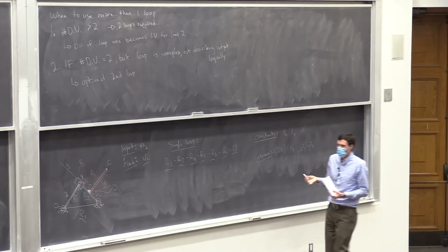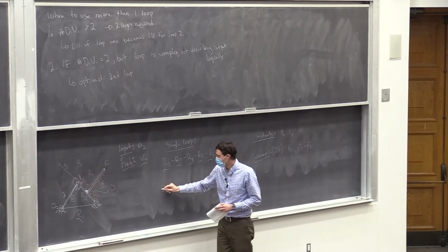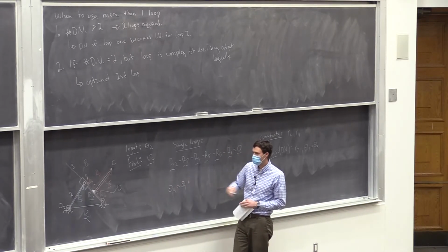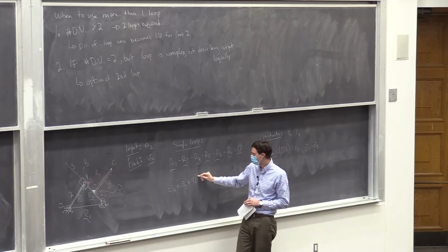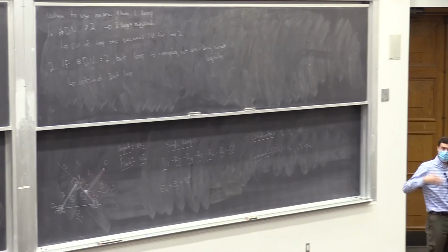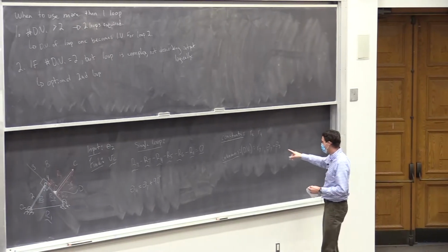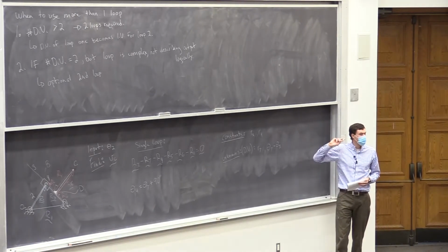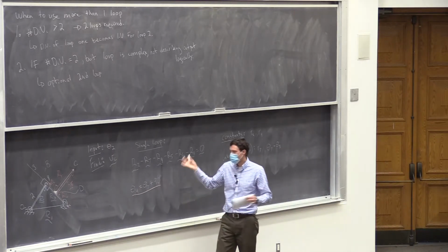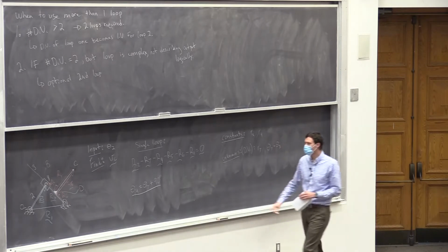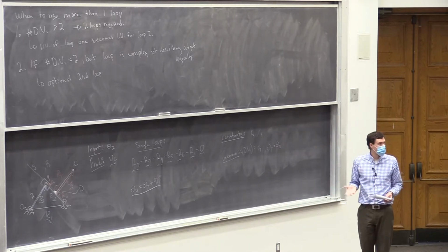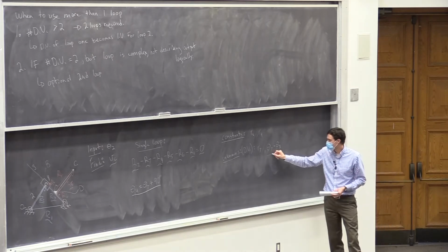So that's like a relationship that we know. Theta 4 equals theta 7 plus 90 degrees. So that's like an additional relationship that we know. So it's up to you to decide if you want to call that an unknown, you can. And you're going to need more loops to solve for that. Or we already know this relationship. So it's probably better just to use your relationship. It's very simple. And now theta 4 is not going to count as an additional unknown because we already listed theta 7.